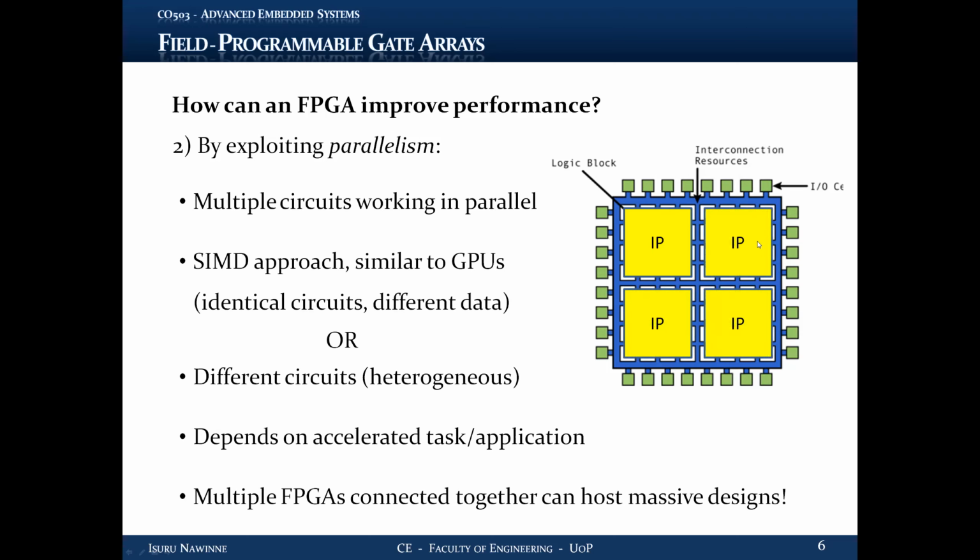So if your application can be parallelized, FPGAs will allow you to gain much better parallel performance compared to general purpose systems, because at the logic block level you can get parallel functionality. This is very similar to GPUs, the SIMD approach, single instruction, multiple data. If you have a small IP block, you can put n copies of the same IP block on the FPGA and get them to work in parallel on data.